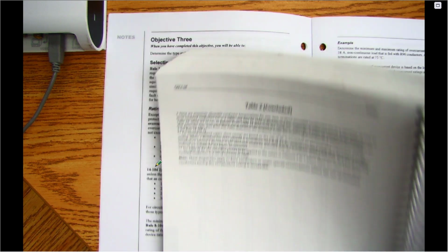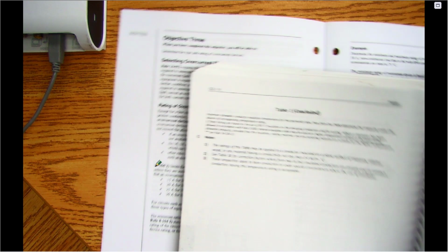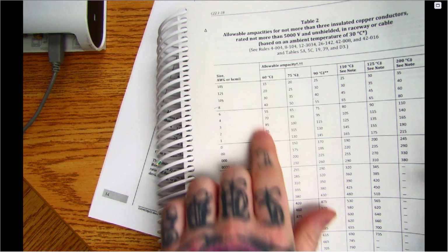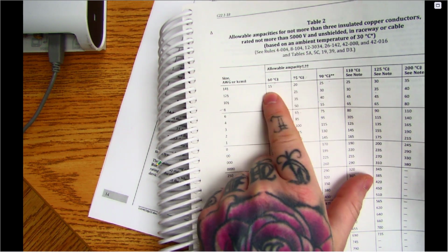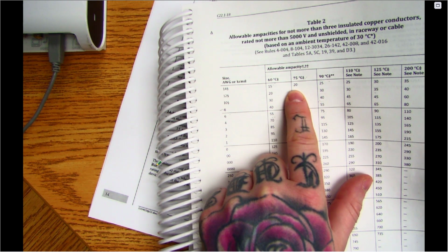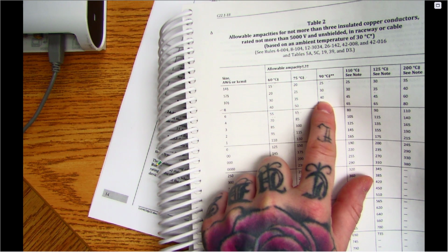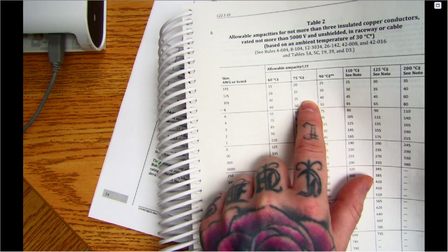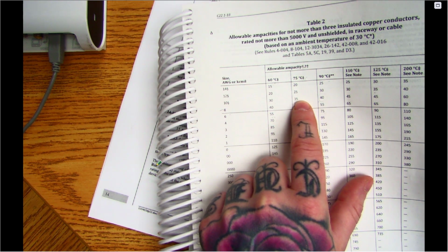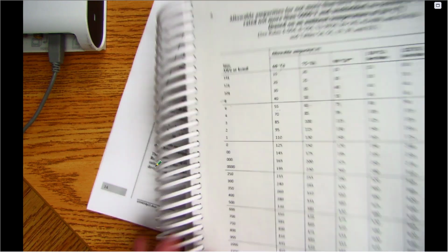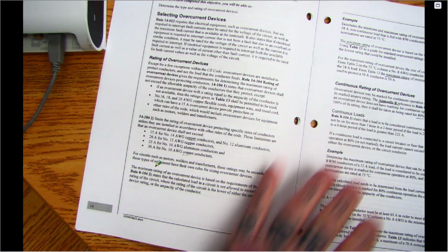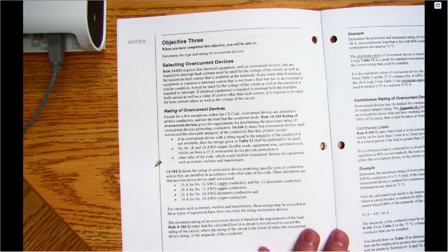Okay, and that's going to tell you that even though the ampacities for these wires are larger, depending on what temperature you're going to use, right? So that's kind of the caveat. They're saying, hey, even if you're going at 75 or the 90, I can see these are rated for higher values of current, but in general, we're still going to limit the overcurrent that you can put on those wires. Okay, so that's an important rule there.